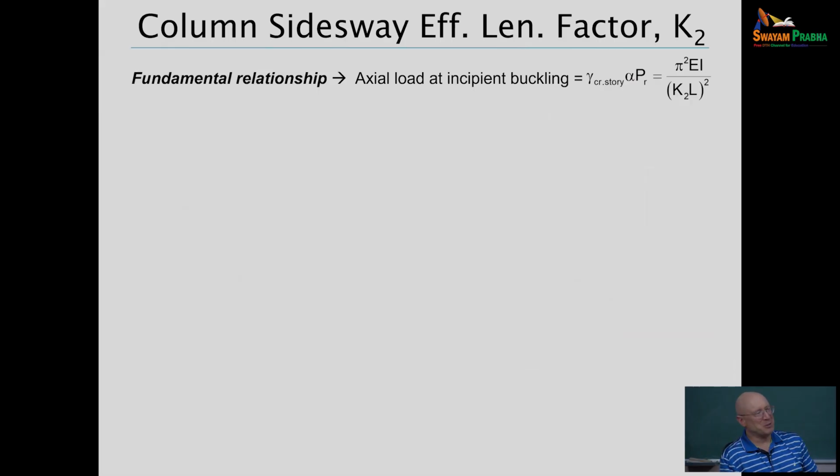All right, we talked about the effective length factor K1 for non-sway yesterday. And again, remember, I emphasized at the beginning of class today that you don't need the K factor. You just need the axial force in the member at incipient buckling, when you design from that. So if you're using computations, you can work straight from that.